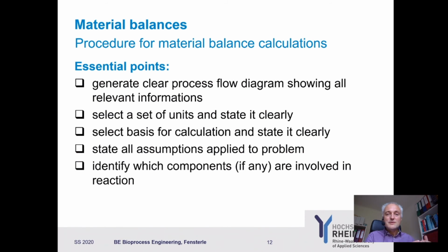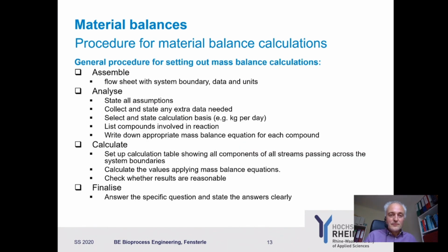you know what mass balance you can apply, because for all components in the reaction, you can have a generation or consumption of the components. If it's not in the reaction, it's just M in and M out. So this is something you should collect at the very beginning.